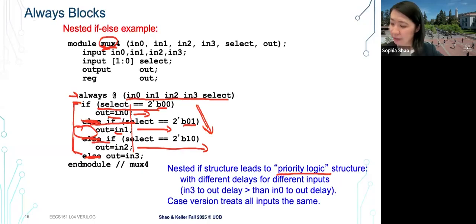That's a good question. Let me give that a try. Actually, I don't know what hardware it will generate. I'm pretty sure it's about the same. I think we'll just have 4 parallel comparators. It's still the same select, and you will do 4 parallel comparators, and then you probably need some output select in parallel, because you keep reassigning the value to the same output signal.